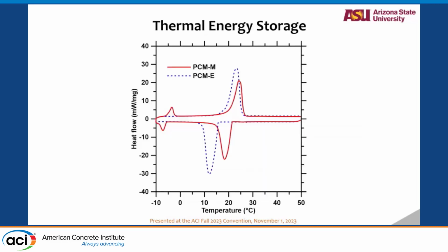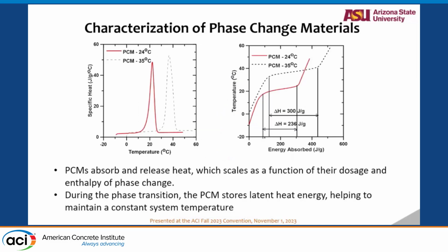We did a thermal energy storage test of both the PCMs to see when they store heat. The range usually stated is around 25 degrees Celsius, and we saw that it's the general range that they showed. The above one is the heating procedure while the lower one is cooling. The storage of heat during heating and cooling does not usually happen at the same temperature.